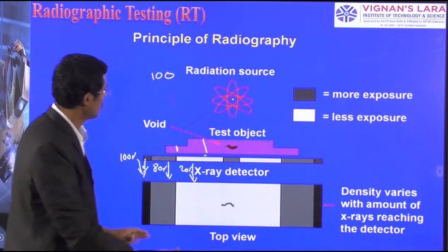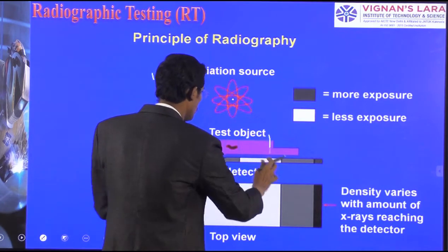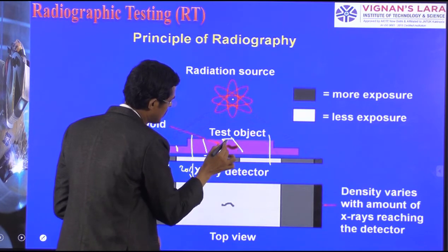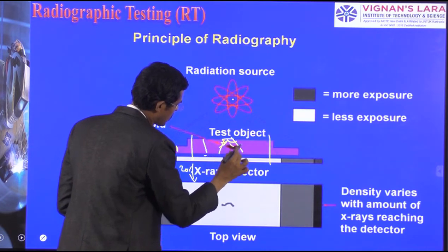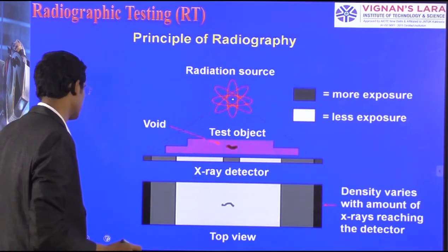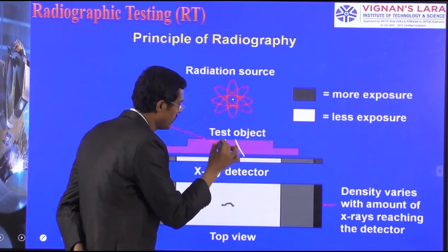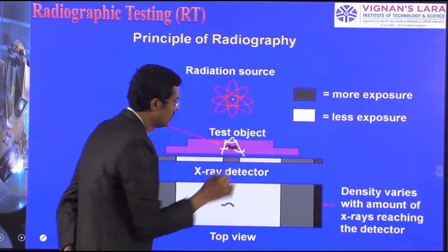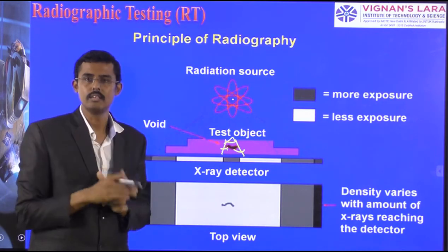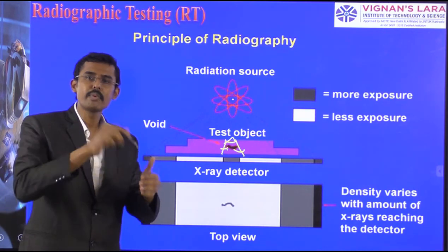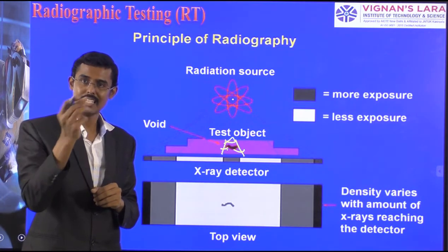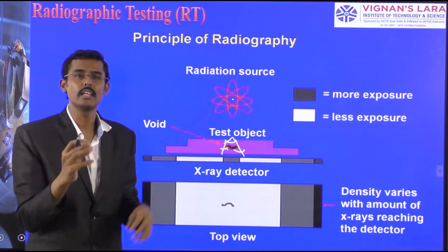Now, let us consider our zone is welded here. Our welding has been done at these locations. In these locations, we have defects. In this location I have done the welding and here I have done the welding. Now I have a defect here. It means I have not welded. Lack of penetration is there. Lack of fusion is there. It means weld metal is not there, the welding process is not done. Then it is a hole.